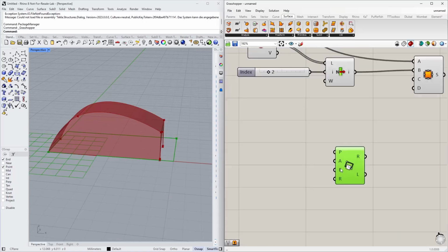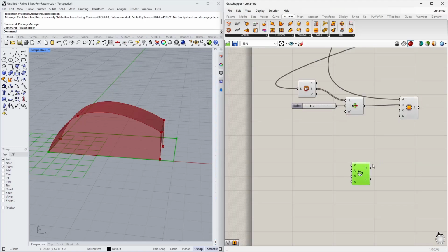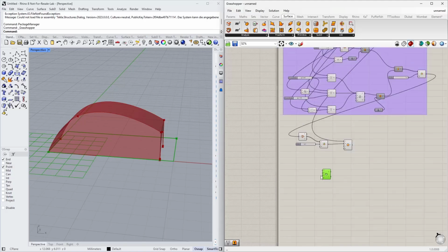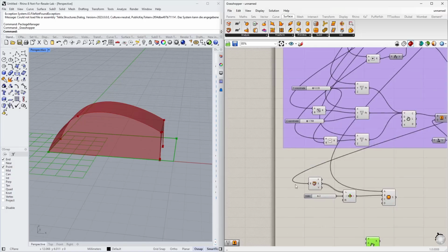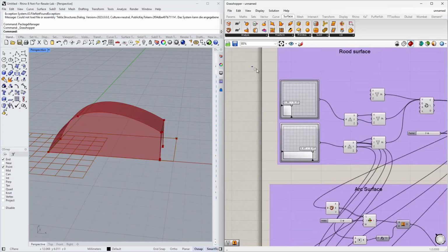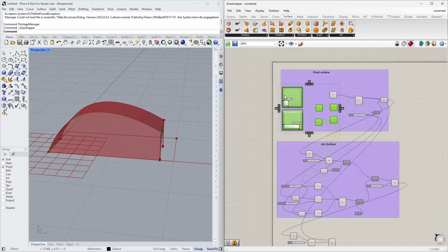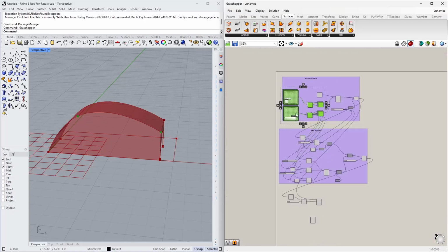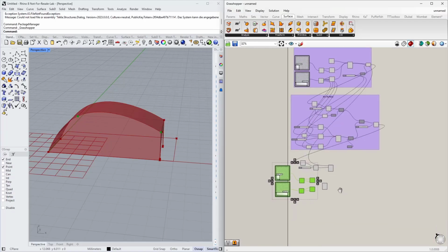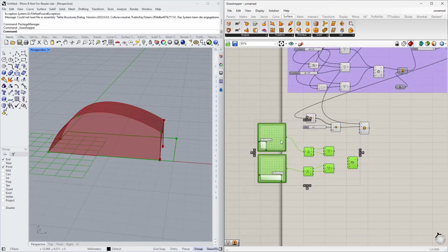Yeah, the 2 points are A and B. And then I extrude the rectangle and then cut it again from the original surface. These 2 definition nodes of the rectangle can or shall be defined again via an MD slider. So I just copy some of those things here, copy, paste, and I will reuse it down here.